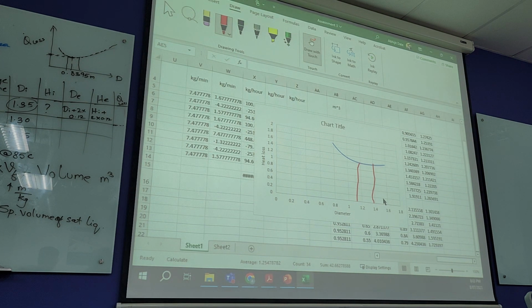But you can use mine first. It's the heat flux times 2 times pi, then times diameter divided by 2, internal diameter, divided by 2 times internal height, then plus 2 times pi times diameter divided by 2, all internal.